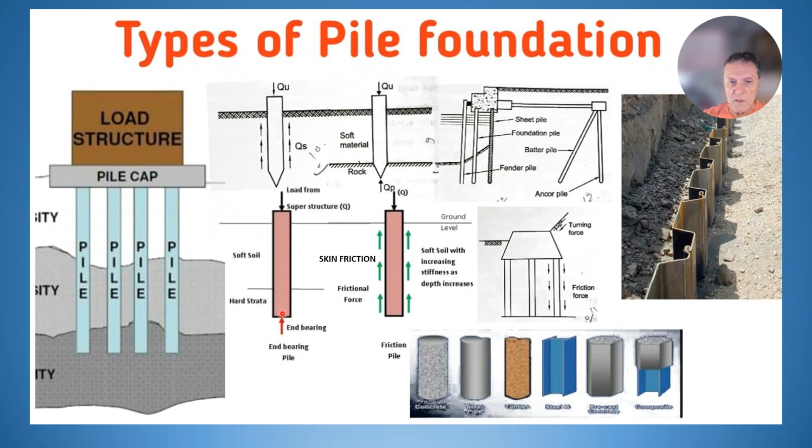You have soft soil, you have hard soil. Here's the frictional force caused by skin friction, which gives you more strength around the pile itself. The deeper you sink a pile, the more skin friction you have, and the better that pile will be held in place.